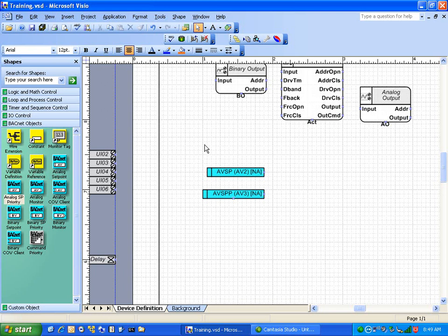And I found out in the summertime we were rebooting UNCs about 3 times a day because the communications were all bogged down. We got into a call with Schneider about it and everything, and found out that I had to remove all of those. So whenever you're writing directly something live that's always updating in the priority array, you're kind of hogging up your BACnet communications a bit.